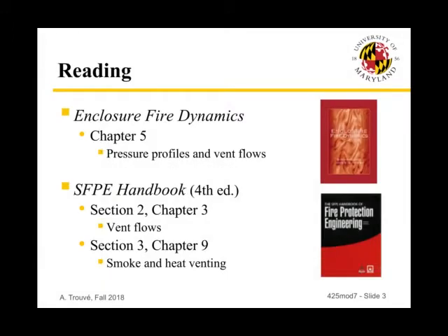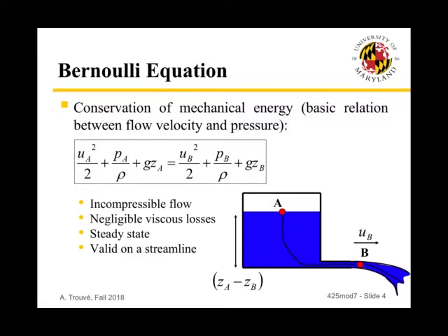All right, so this material is discussed in chapter 5 of the textbook, and you also have here 2 chapters from the SFPE handbook which bring additional detail. The basic description of mass flow rates through vents is based on the Bernoulli theory, the Bernoulli equation. So here you have a reminder of the Bernoulli equation.